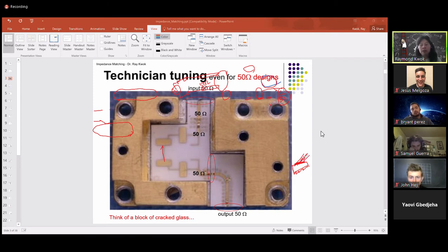So like here, going through this, that's a very narrow line. So that's my high impedance line. Going from here to here, that's very wide, right? This is the width, so this is the low impedance. High impedance is equivalent to an inductor. Low impedance is equivalent to a shunt C. So this is a series inductor, and this is a shunt capacitor. So I have high, low impedance. This is one way to do a low pass filter, so this is a low pass filter network.